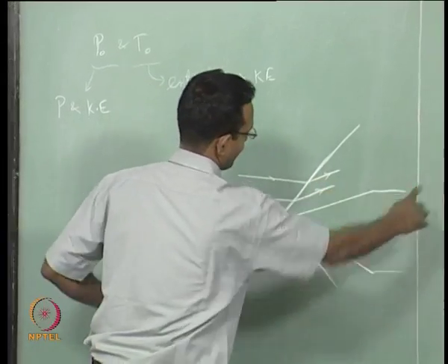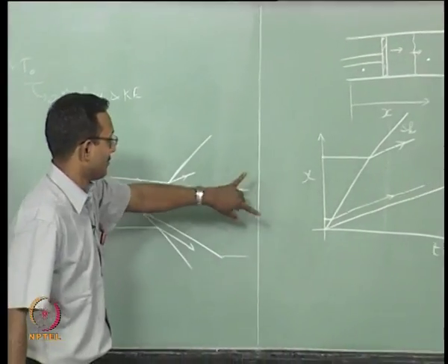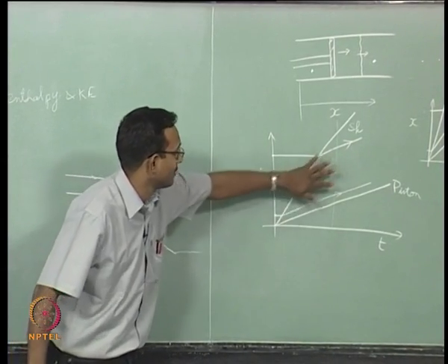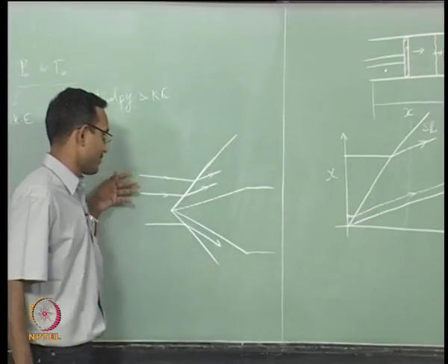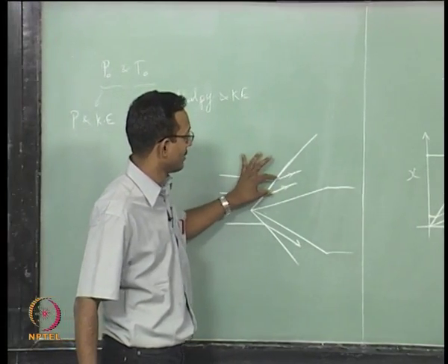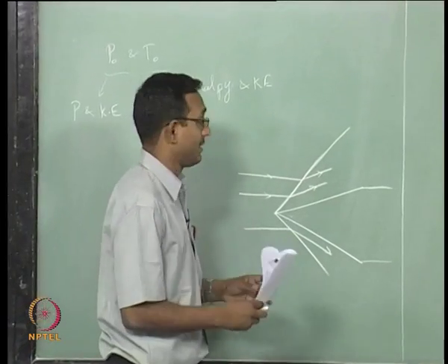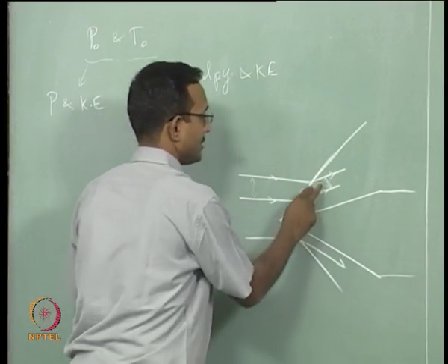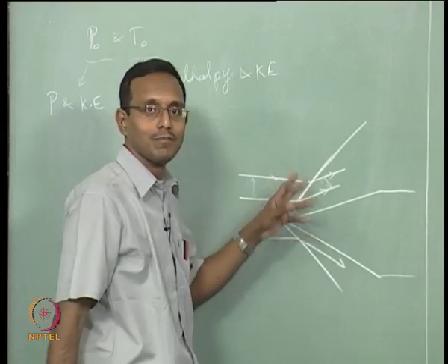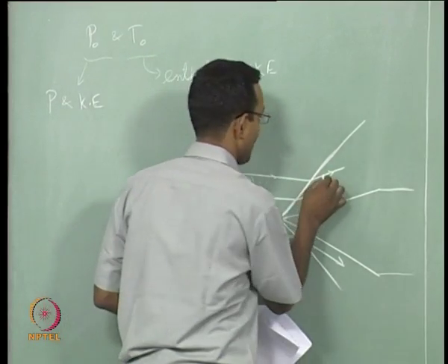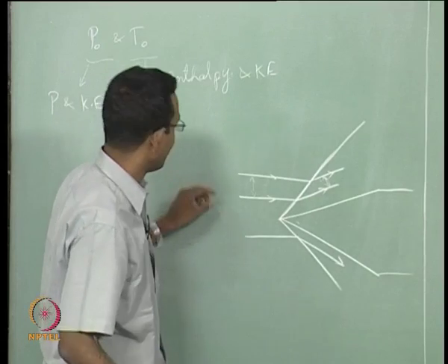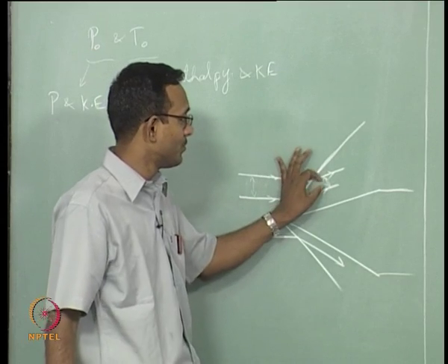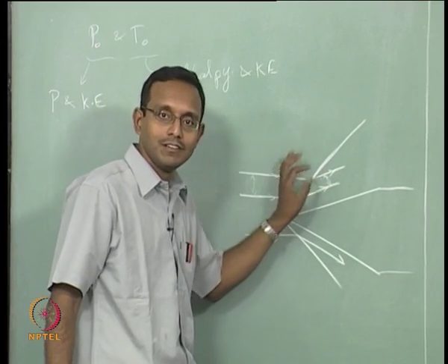Similar to that picture which we had here, there are two streamlines coming here, they are going to meet the shock line and then they are going to turn and go along the wall. Same thing happening here, parallel initially, and they are going parallel to the wall. If I look at it, the streamlines have come closer, this distance is less than this distance, okay, which tells me that the fluid element sitting between these two, considering this as my stream tube, has gotten crushed, which is my compression.